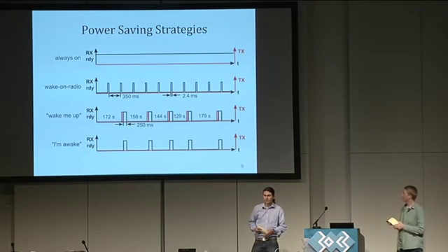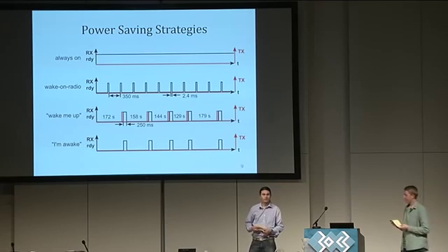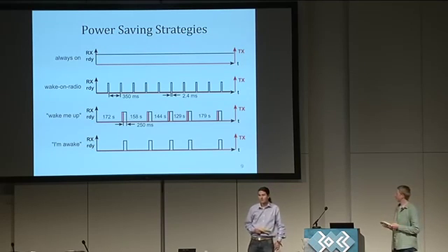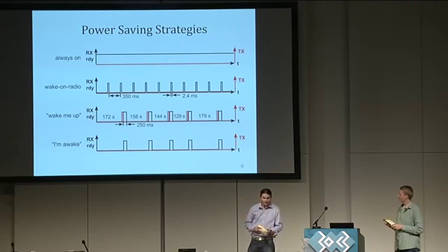The device wakes up to receive ready mode for 2.4 milliseconds, and after that it falls asleep for 350 milliseconds repeatedly. So it can react on packages almost immediately.